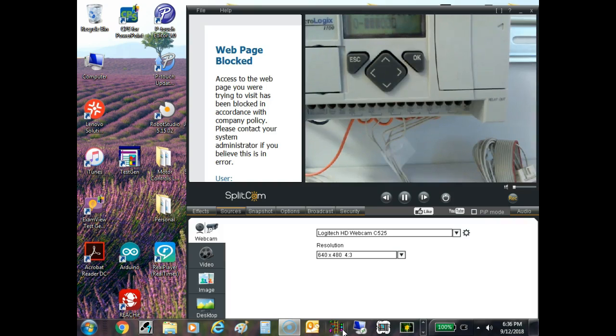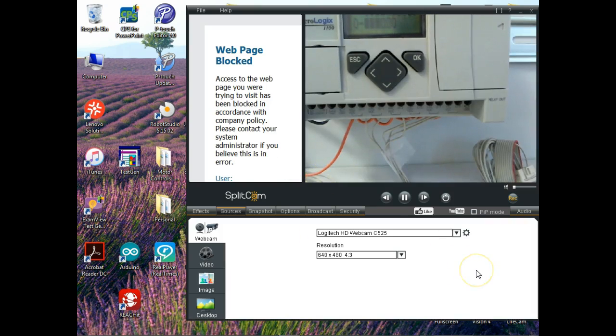Probably the most popular, and probably used well over 90% of the time, is ladder. We'll introduce y'all to the function block in other classes, but we won't do any of that programming here. So what they've done is they set a path up for people who come up through programming, computer people, who understand Pascal programming languages. If y'all have heard of that language before, they have a language called structured text, which is basically very, very similar to Pascal.